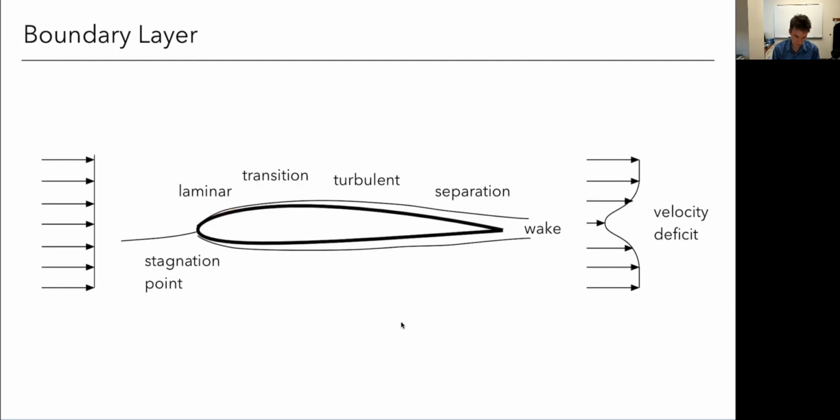Sometimes, in fact, when it occurs in the laminar region, say here at this high angle of attack, we could get separation early on, and the flow, if it's so early, can even reattach sometimes. This is called a laminar separation bubble. But that's a less common scenario. We'll notice from this figure the presence of two types of drag.